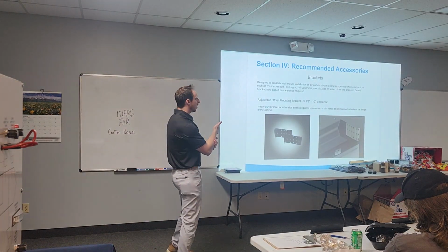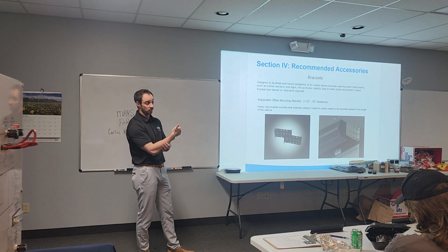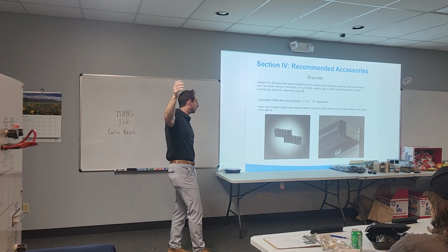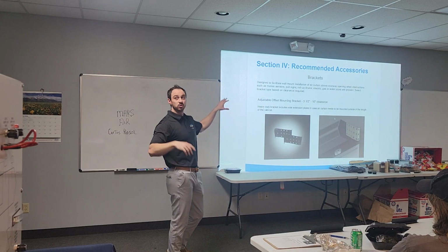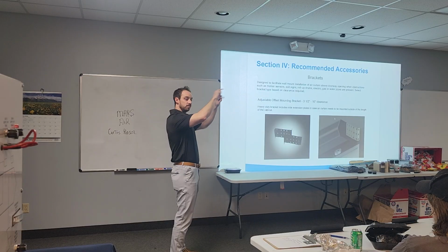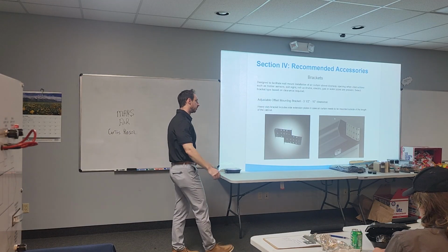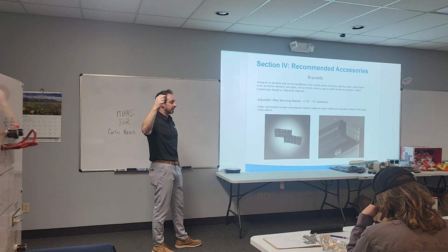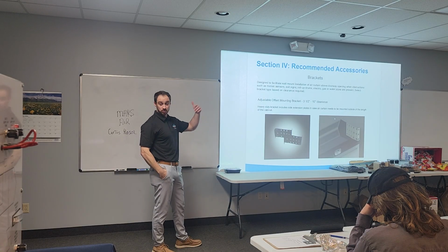The last thing is brackets. A very common question, and misconception, is: do I need the brackets? And the answer is no. Typically the units just mount directly on the wall above the door. Very straightforward to install. For the majority of our commercial units, they come with a back plate. You just bolt the back plate right above the door, and then the unit pretty much just clips onto the back plate. Our larger units are typically hang mounted by threaded rods or something like that, but if you had to mount them on the wall, you can do that as well.